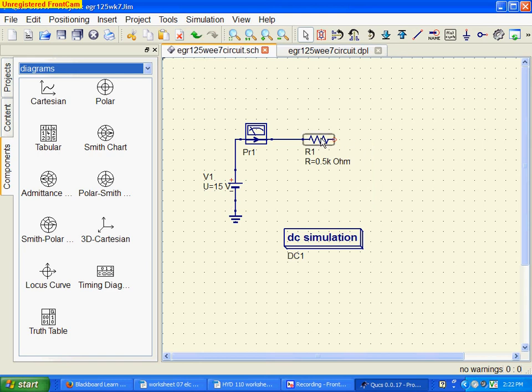And I'm going to wait. And it's finally showed up. I'm going to click where I want it. It copied this resistor identically, same value, everything, but it did give it a different number. I'm going to escape because now anywhere I click, I'll have another resistor.